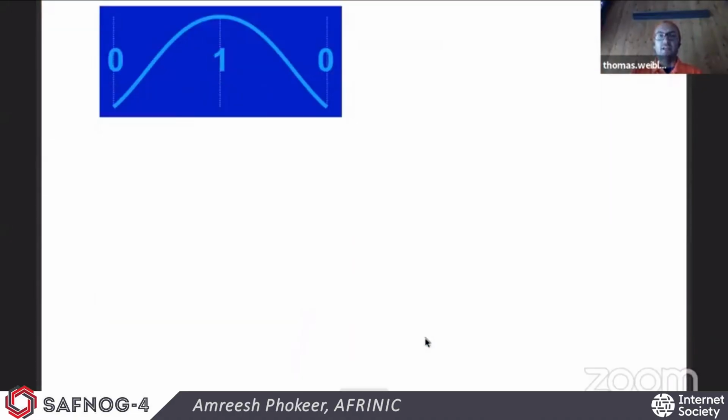Looking at our rectangle shape, we have here two events, 0, 1, 0. A signal having 3 states, 0, 1, 0. And the rectangle shape is no longer a rectangle, it's more a sinus, as we are talking about high-speed signals. The sinus which you see here on the screen is actually our rectangle, which I showed previously on the theory page.